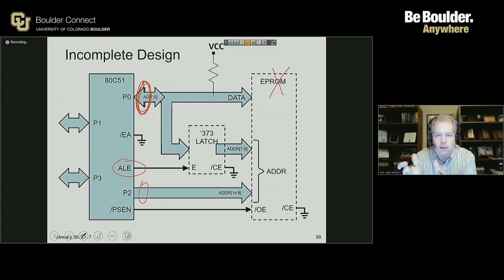If the clock speed is 11 megahertz, a machine cycle is about 1 megahertz. So that's about 1 million machine cycles per second. So it can go through all these combinations really quickly, and before you know it, it finds one of the combinations which hits the PCON idle or PDE bits and shuts it down. We want to avoid this because if we're tuning our oscillator circuitry, we need to have the system up and running in a stable way.